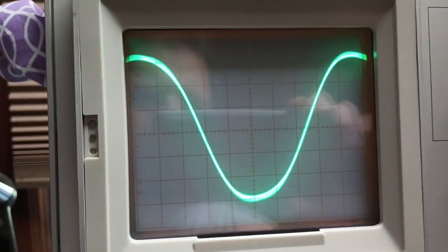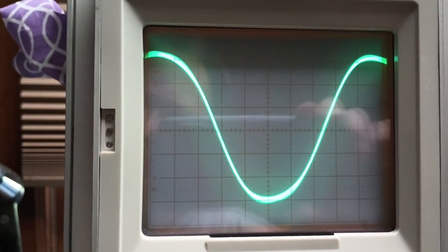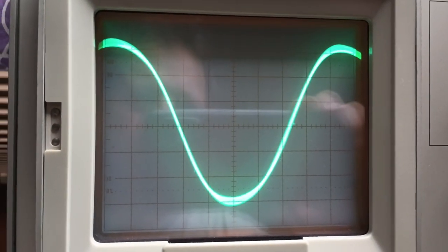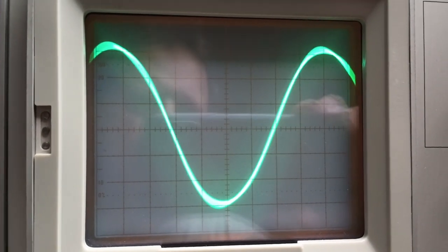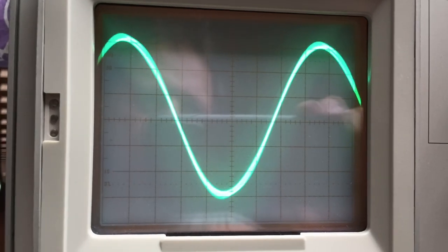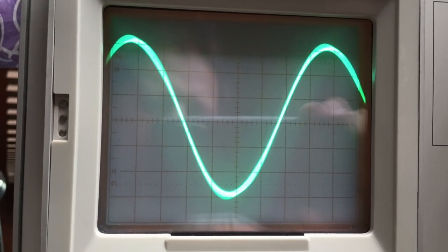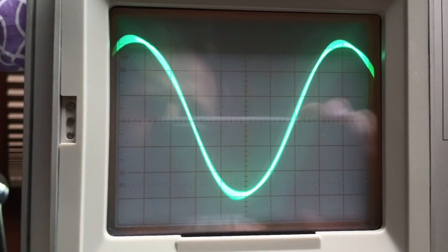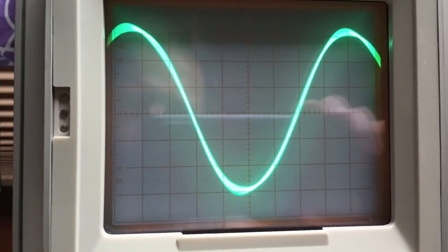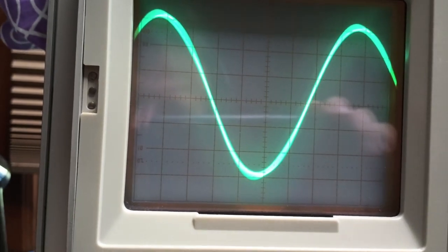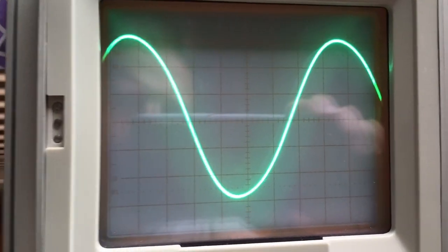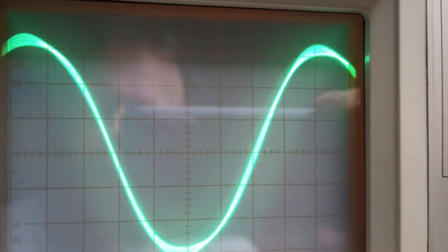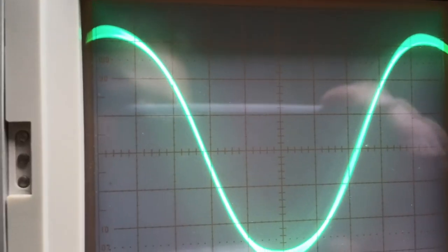So here's a wave shape. When I change the frequency, 20.9, 21.0, 21.1 is optimum. You'll see the peaks of the wave, how thick they are, and now it's all the same. There are several sine waves lining up there. There may be 5 different sine waves implied here. And at 25 megahertz, they all line up at the same time. But notice on the top, as I go down through 23, 22 megahertz, 21, they're all pretty much lining up.